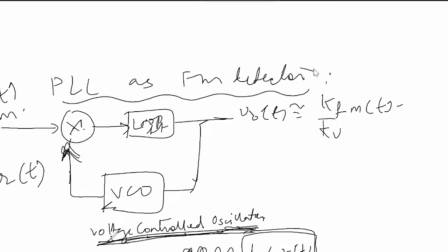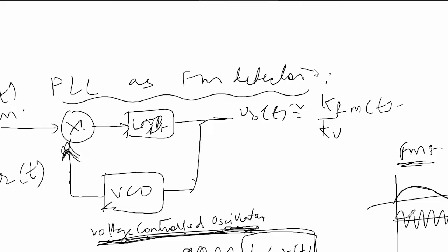This means that the voltage controlled oscillator has the ability to produce an FM signal by itself, because the very concept of FM is that in frequency modulation, if this is your message signal and this is your carrier signal, the frequency of the carrier signal is increased and decreased according to which signal? According to the message signal, isn't it? That means the frequency of the carrier signal has changed according to the message voltage, and that has given us the FM signal. A similar process is taking place in the VCO.